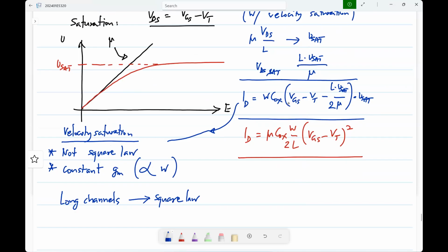Okay. So other things you're already aware of, that the small signal output conductance of the MOS transistor is basically dependent on the length of the transistor. So if you want high gain, you have to use long channels and so on. Okay. So any questions on any modeling related stuff that we have discussed? So body effect is something probably new, and then maybe the weak inversion operation. Okay.